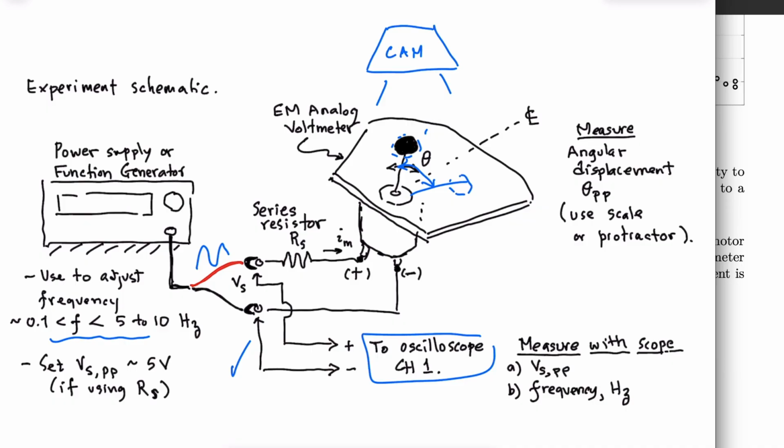So we would have to have a way where theta and voltage in are being measured simultaneously, because if you wanted to measure phase, you have to be able to look at those signals together. And as of yet, I don't have a real clean way of doing that that we've implemented. But it's good enough to get magnitude data, and then if we can fit that to a model, then we know it's second order in our case, and then we'll know what the phase looks like.